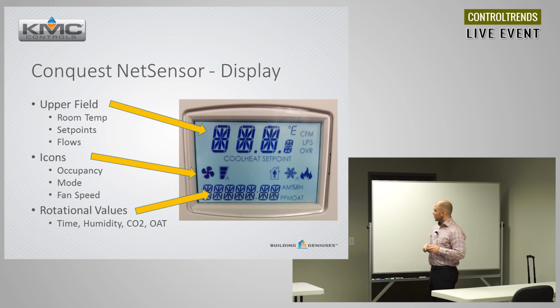And we'll show you a picture of the display all lit up with all the segments. So we have an upper field where you traditionally see room temperature, set point, flows if you're balancing. Icons for fan speed, heat cool mode, occupancy levels. And in the bottom I have a rotation of values field, with things where you can set time or show time, humidity, outside air, maybe you're going to show discharge air. Again, any points you want to put in there, if there's more than one configured, we'll just rotate through and show you all of them.